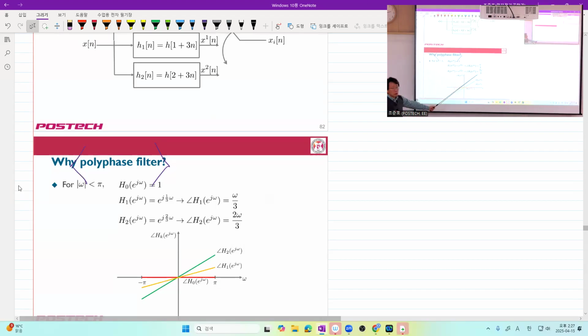The second one also has linear phase shift. And what's the meaning of linear phase shift, by the way? Delay in the time domain, as you learned in signals and systems. And actually, having an ideal low-pass filter means that your interpolation filter is a delta function. And a delayed delta function gives you linear phase shift. Of course, in general, your filter is not an ideal low-pass filter.